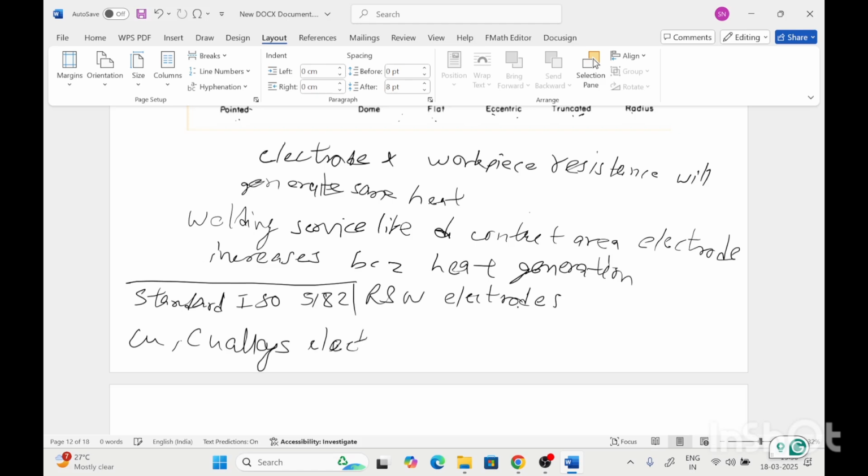Sometimes the stainless steel or the galvanized steel have zinc coating on it. So the zinc can also diffuse to the copper electrode with time. Because of this diffusion, the copper composition will change and form brass, meaning copper and zinc alloy is known as brass.